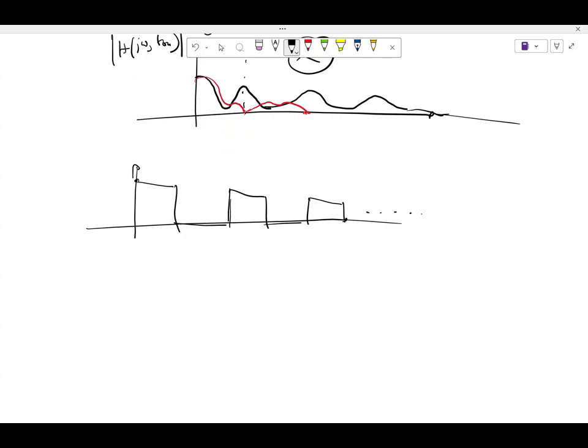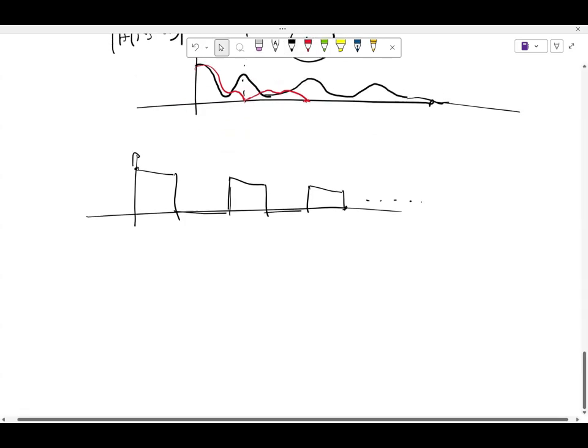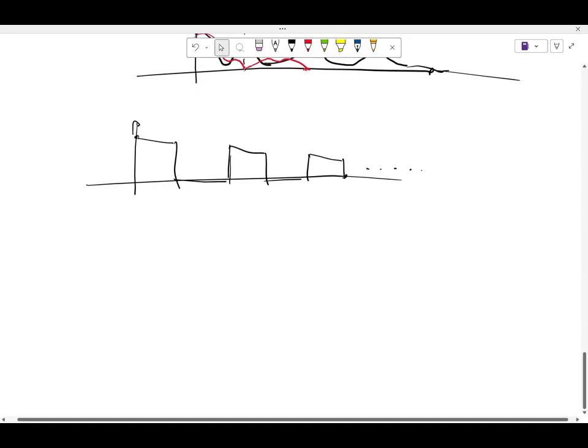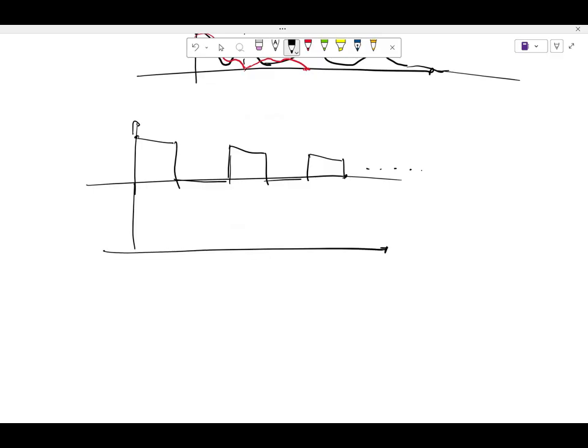So approximately, what I'm going to tell is an approximation, not strictly true, but you should be able to appreciate the fact that if the RC time constant is much higher than Ton, it probably looks like I had a continuous decay like this, and I have chopped it off somewhere here, right? So clearly, this and this are not equal, which is a matter of detail I'm ignoring.